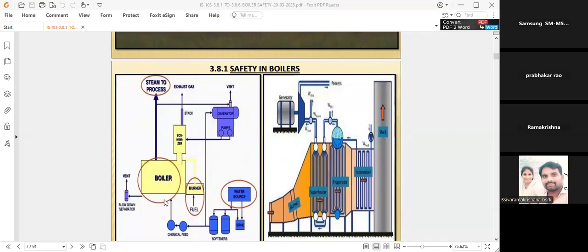What does the boiler mean? It heats the water and prepares the steam by burning the fuel, with the help of the oil. Steam to turbine: the turbine's input is HP steam, and its outputs are power, MP steam, LP steam, and condensate. The turbine has a double extraction system. It will give not only MP steam, but also LP steam and condensate.